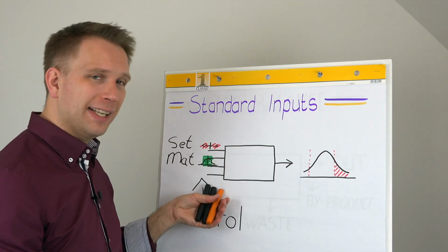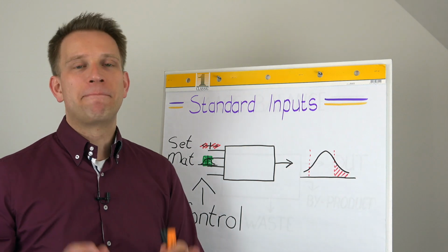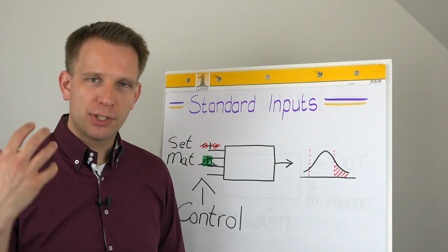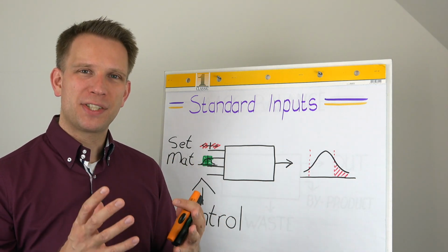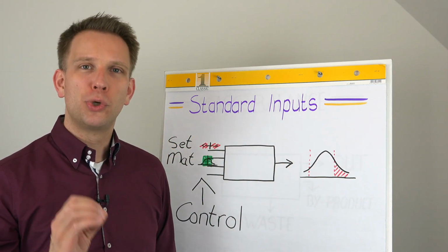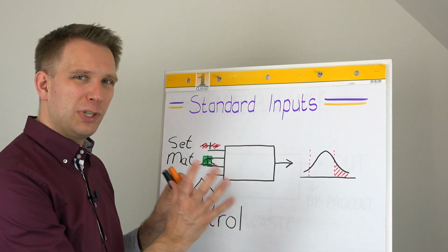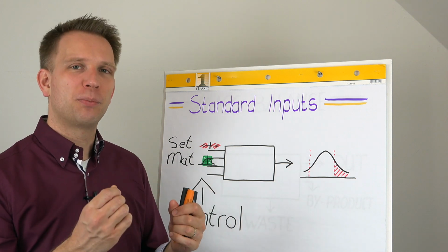And when we check this list, and it's all okay, but we get a bad product, you can be pretty sure that you need to call in some maintenance engineers, some product technologists, some people with good root cause analysis skills, but also good knowledge of this whole process. Do not try to solve such issues with only a few operators discussing about how to set the line. You have a different problem here.